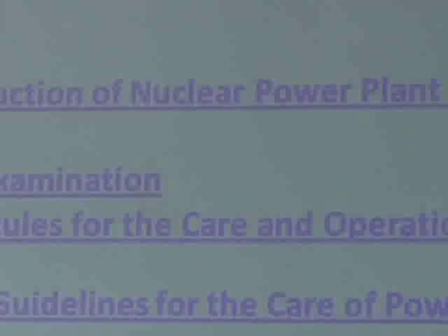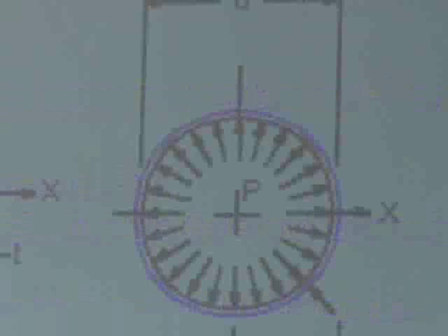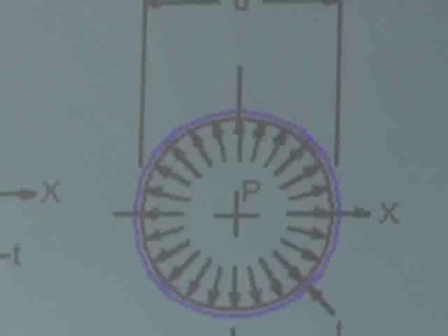They have additions to it, so it says pressure vessels, but people will still sometimes use the same code for designing other things that are not going to be pressurized. It becomes up to the designer. We talked about AWS last time as a way to say, make my welds this way. So this is another one. And if you're making a special structure, you have the option, essentially, of going with ASME or AWS, American Welding Society.